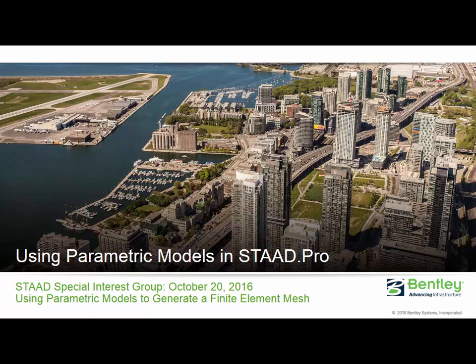Also, during the process of meshing, the program will automatically take into consideration existing nodes that lie within the boundary of the panel, which is actually a huge advantage. You simply will just have to define your panel boundary, and then the remainder of the nodes will automatically be considered as control points, which is to say that the elements will be created in such a manner that some of those elements will have these nodes in their incidence list. Control points may be panel points of a truss which supports a multi-span slab, or a foundation slab that supports several columns.